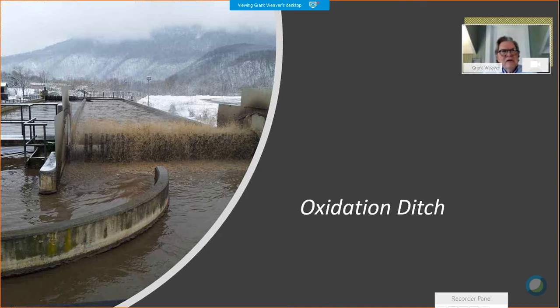Because dissolved oxygen is a measurement of how much oxygen there is in the tank. The ORP is a measurement of what the bacteria are doing with the oxygen. So the bacteria aren't going to be breathing a lot of oxygen until the oxygen is there. So that activity, there's a little delay. So for that control, DO is a good control to see when you have the oxygen to a favorable concentration.